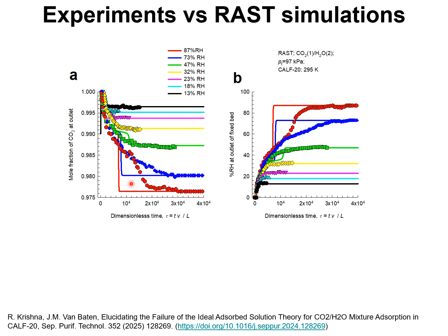The comparisons with the experimental data at the 2 highest values of relative humidity, 73% and 87%, is significantly poorer because the experimental data on the component loadings determined from the experimental breakthroughs show that the water loadings in the adsorbed phase exceed those of pure component water.